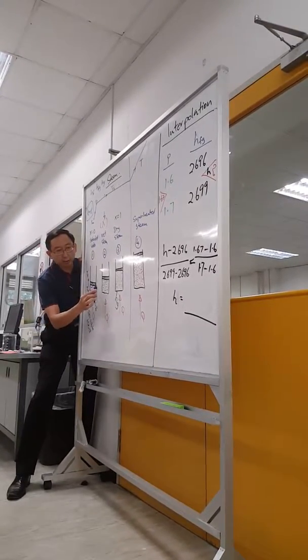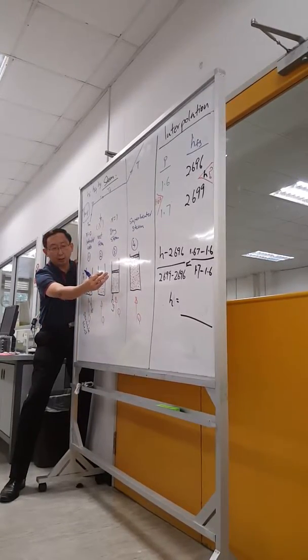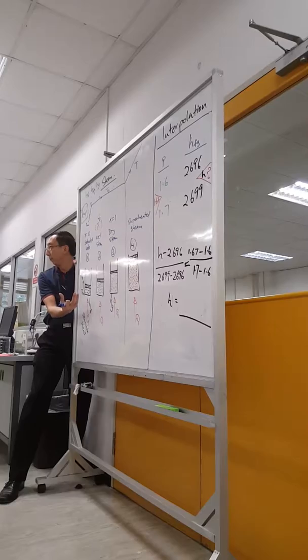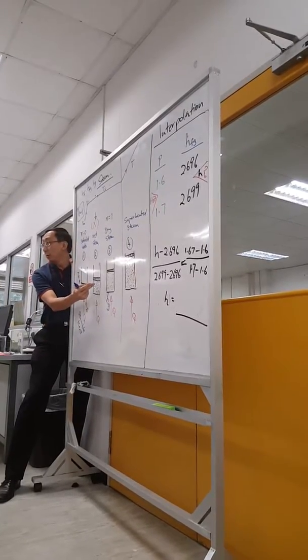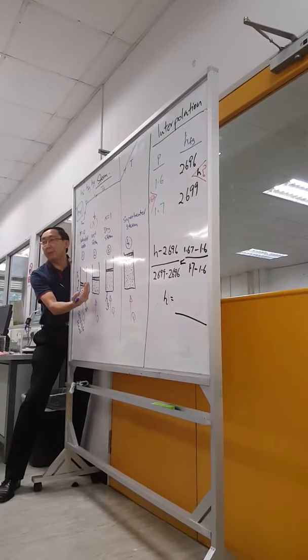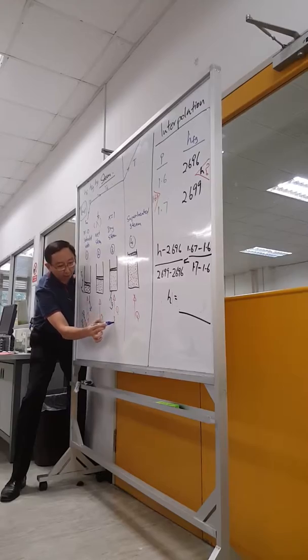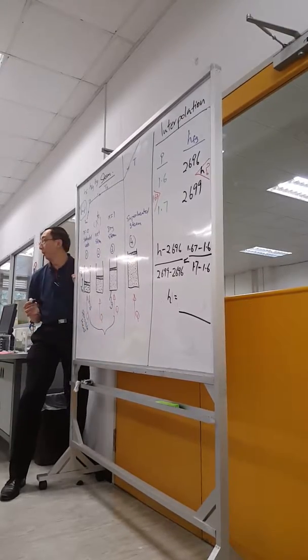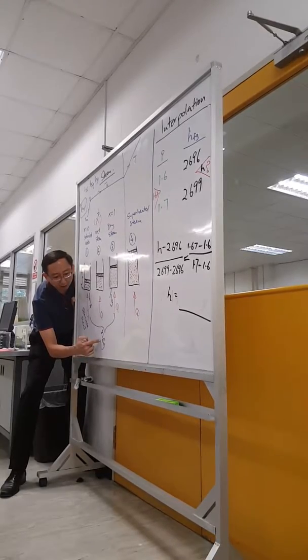And in order to reach HG, from water to steam, totally dry, I need to pump in more energy, right? So I pump in energy to convert, but it is not enough. Some of them are still wet. I still need to pump in some more energy to convert them all into dry. This amount of energy from here to here, to get them to dry, is your HFG, from liquid to gas.